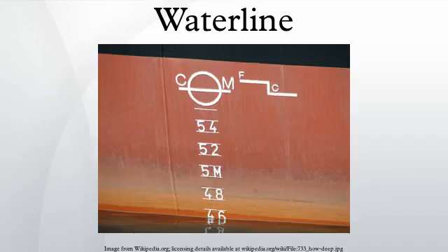Freshwater is considered to have a density of 1,000 kg/m³ and seawater 1025 kg/m³. English densities are 62.4 pounds per cubic foot for freshwater and 64 pounds per cubic foot for seawater. Freshwater marks make allowance for the fact that the ship will float deeper in freshwater than saltwater. A ship loaded to her freshwater mark in freshwater will float at her summer mark once she has passed into seawater. Similarly, if loaded to her tropical freshwater mark, she will float at her tropical mark once she passes into seawater.